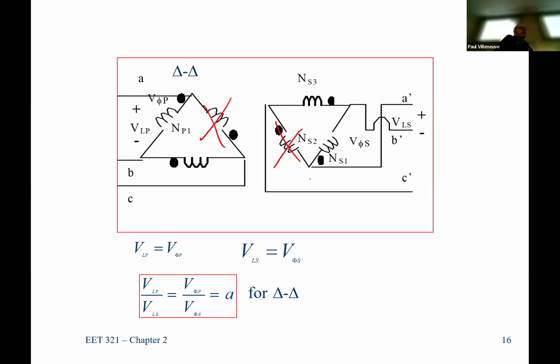How about not exactly, but sort of? Because what does KVL say? The sum of the voltage drops on a closed loop has to be equal to 0. If I get 1 at an angle of 0 voltage drop over here, I get a 1 at an angle of voltage drop over here. This leg is open. What would I measure between these 2 points?